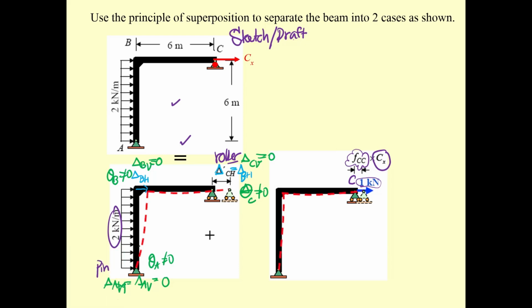And we can indicate this is going to be your theta sub A with respect to the tangential line. And also for this one, you have to draw it with respect to the tangential line. For the theta sub B, you have to draw the reference line and draw the original tangential line of this one. That's going to be theta sub B.